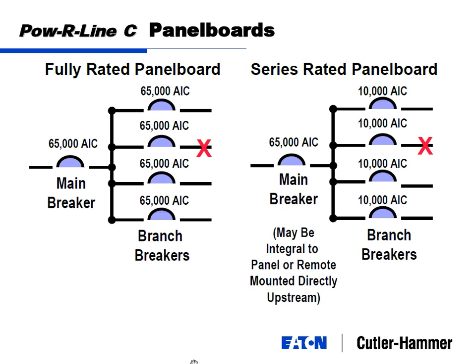So when I'm sizing this breaker, I'm sizing it to the continuous current carrying required. How much current am I carrying? If I have a 200 amp panel board, all the wire upstream is going to be sized to 200 amps. It's not going to look at this number, because that would be the service entrance. Yeah, this is the withstand capability. So I don't believe there's any wire that looks at these two.